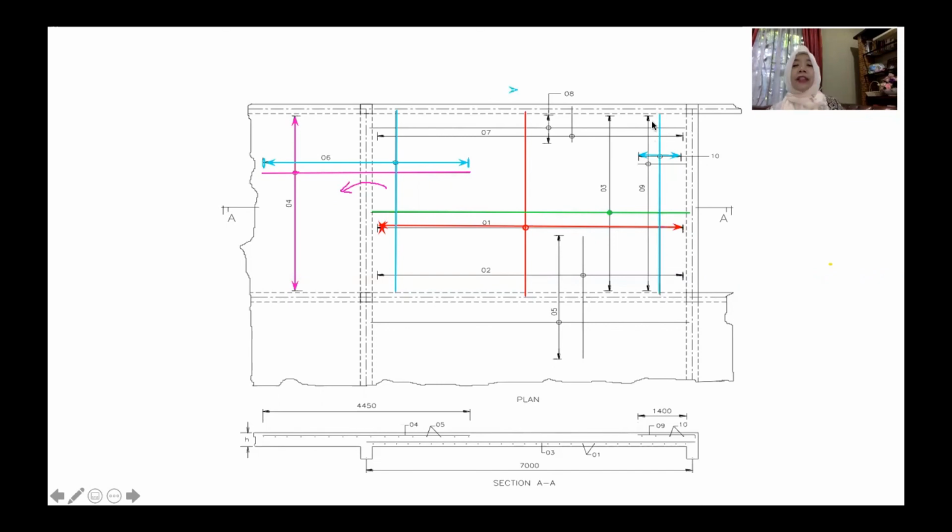Yeah. In the theory, it's said that the torsion must be provided at the corner only, but in the simplified detailing, we need to continue the secondary steel here to avoid torsion from here to here and from here to here.